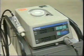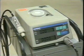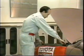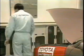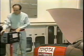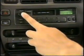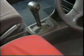Now, let's see how to adjust the idle speed and mixture. You should use a CO meter to do this if possible. First, in order to adjust the speed mixture properly, we must make sure that the following conditions are met. Make sure that all the electrical accessories are turned off. Check to see that the transmission is in neutral.